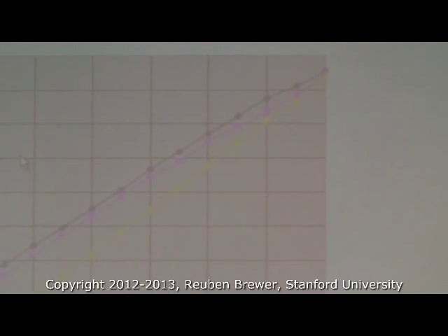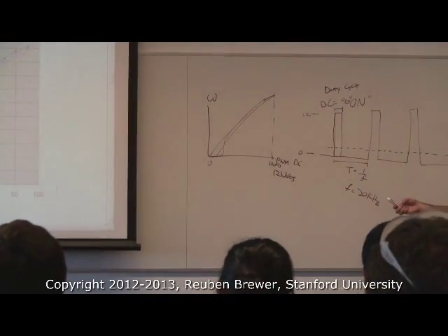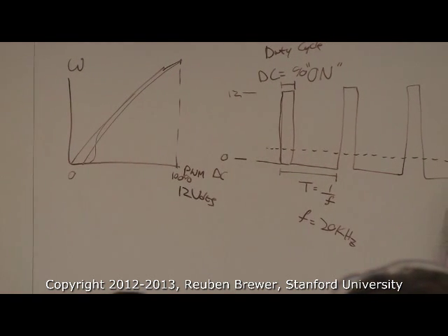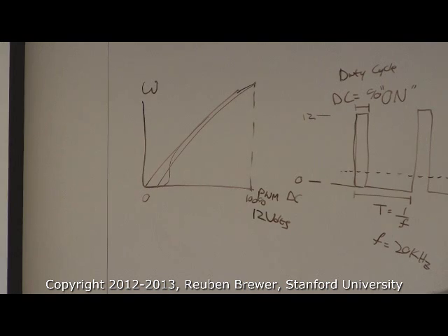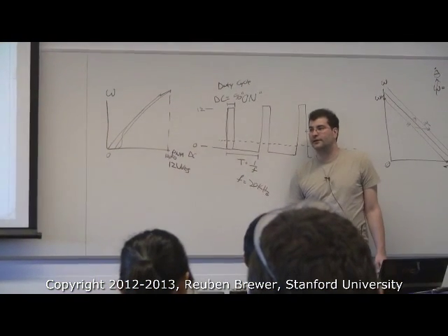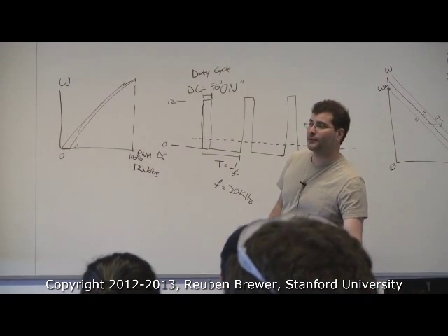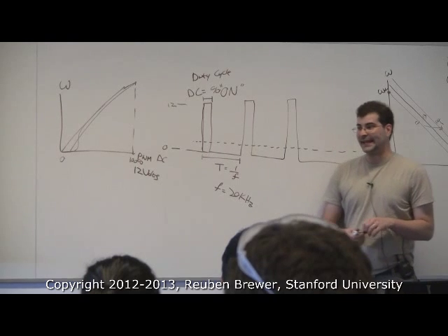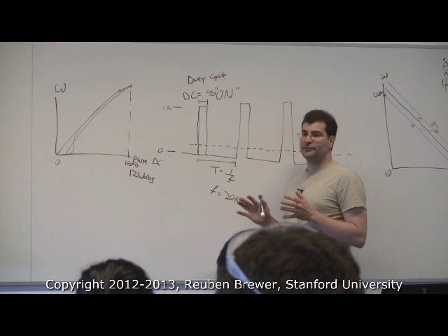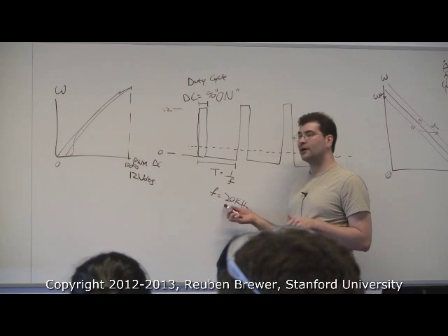So we get another thing. That's for increasing the frequency. So instead of doing 250 hertz, then we do 10 kilohertz, then we do 20 kilohertz. 20 kilohertz is sort of a magic number. Anyone know why? Can't hear it. So if you've dealt with motor drivers that use PWM and they're below this, you hear it, it's really annoying, as I just demonstrated. 20 kilohertz is about the range for typical young adult hearing. So would you want to go at 20 kilohertz?